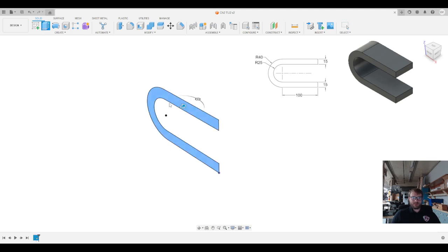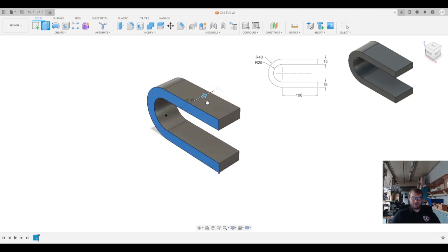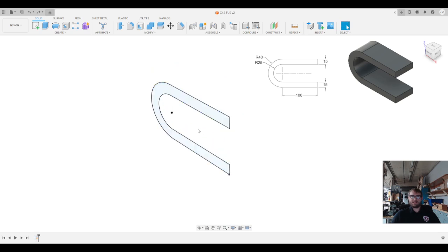That said, we can also extrude this, though that's not part of this exercise, but if you want it to look, and just to confirm that it looks like the picture, we can see that it does look like that when we extrude it, so maybe about 40 millimeters. So that's a step that we'll cover in the next chapter or two, but it's kind of handy to just visualize it right now. So again, really all you need is this sketch. That's what we need for all the test drives in chapter 2. Okay, thanks.